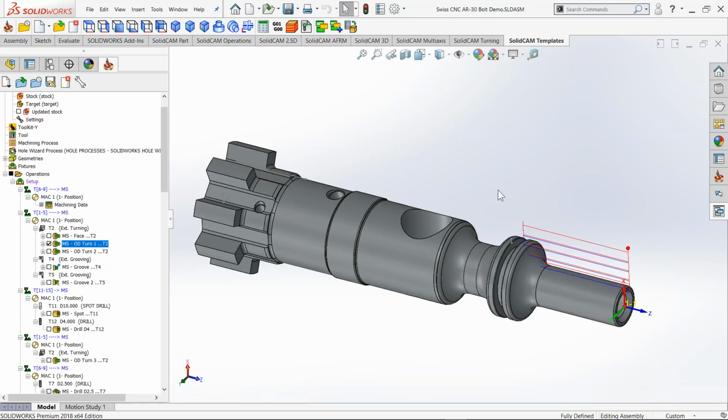If you have the guide bush version, your turning operation must be done in partial, so like a partial machining, like I did in this example over here. So I did a couple of the turnings, going from right to left, finishing all the parts in that strategy.